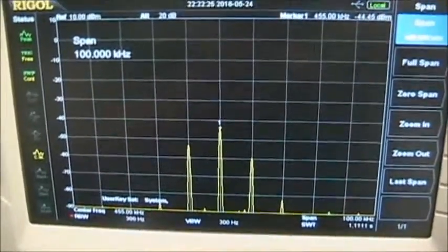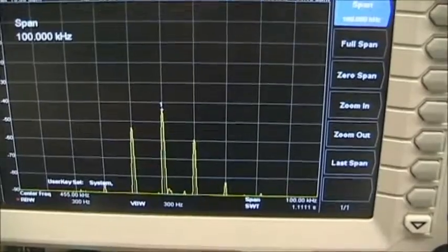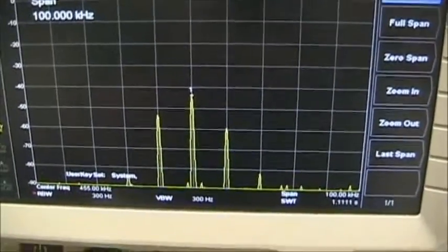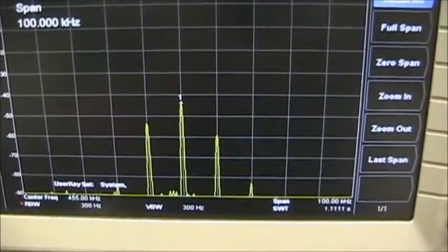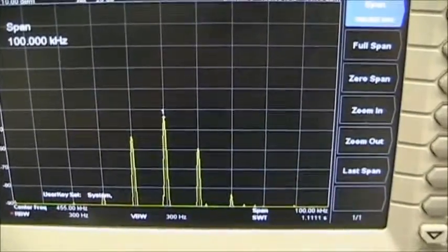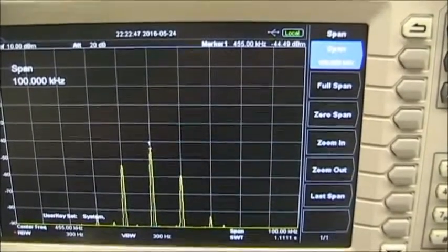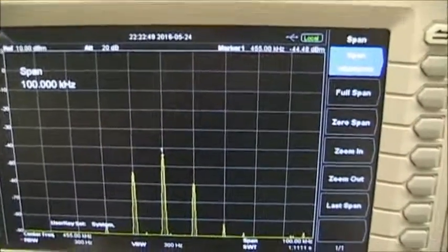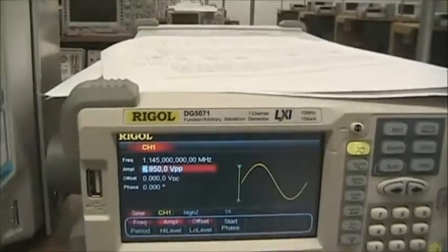Now FM radio uses a different IF frequency, 10.7 megahertz, but all radio systems use this technique. Very few use any other method in their receivers. So that is the end of the lab. Check the handout, and if you have questions, let me know. Please be careful about the signal levels associated with the two generators because the voltages could damage the mixers.